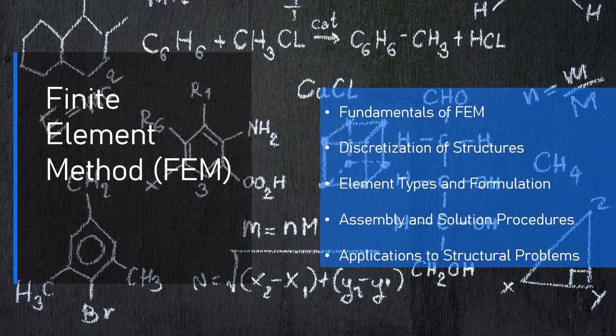However, a finer mesh leads to a larger system of equations and increased computational cost. Geometry compatibility. The mesh should closely follow the geometry of the structure, particularly in complex or curved regions. Boundary conditions and loading. Ensure that the mesh appropriately accounts for boundary conditions and loads. Incorrect mesh alignment with the supports or applied forces can affect the accuracy of the results.